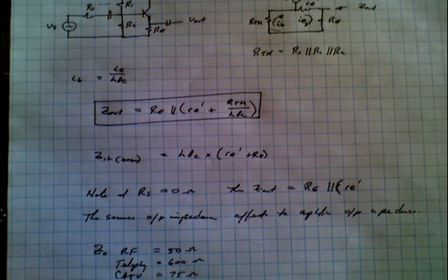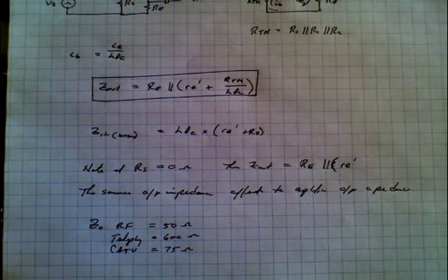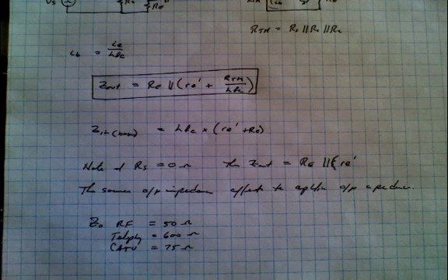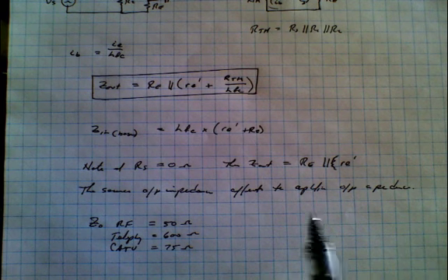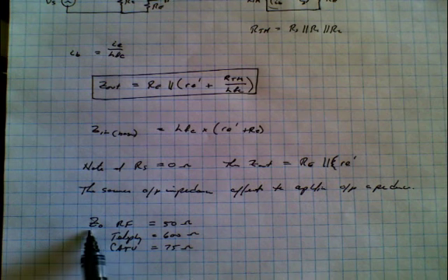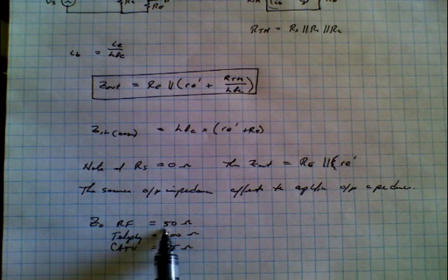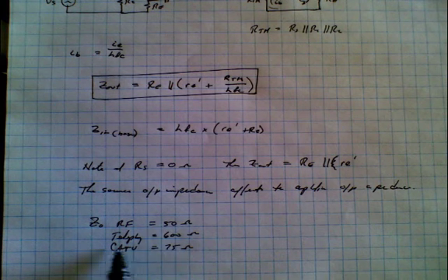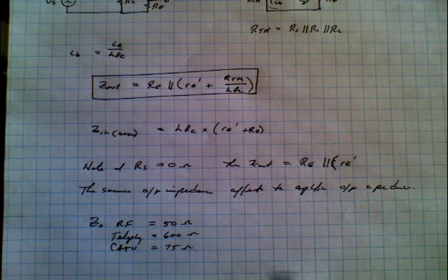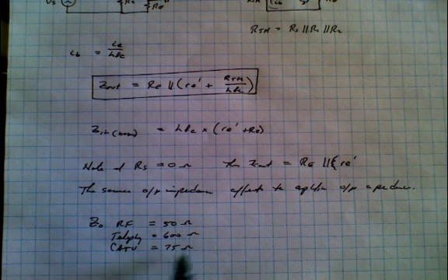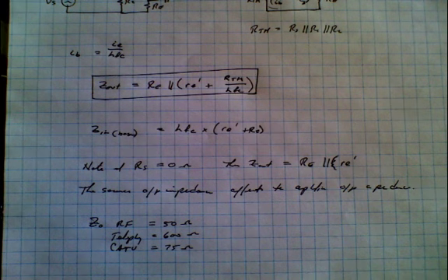Now, many pieces of test equipment and many fields of electronics have specific output impedance requirements. For example, in radio frequency circuits, Z out is typically 50 ohms. For telephony, it's generally 600 ohms. For cable TV, it's 75 ohms, and so on. So one would have to take into account these impedances in figuring out exactly how the circuit is going to respond to any specific input.